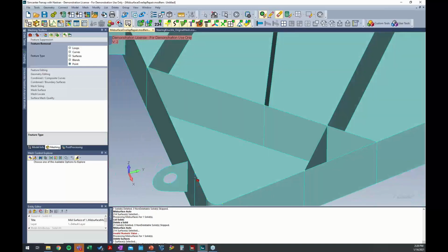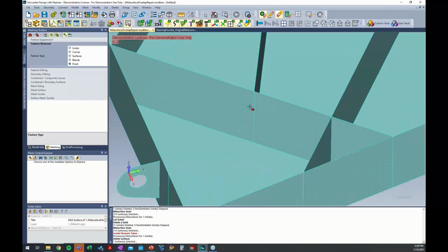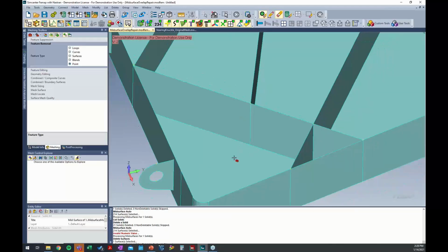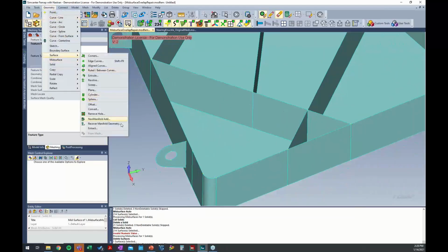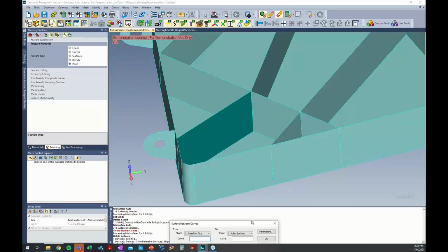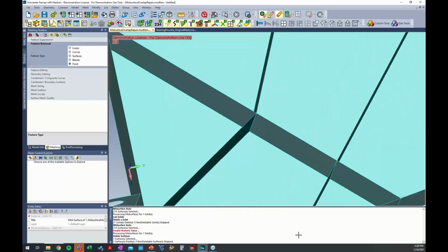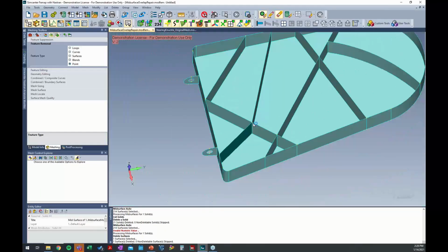And the whole reason that I'm trying to shift these two to line up at the same intersection is for mesh sizing, because that would drive my mesh sizing really far down, way lower than I suspect I would want to simulate. So then I could go to geometry, surface, ruled between curves, select these two, and there's the surface, and it's exactly teed up with the other flange.